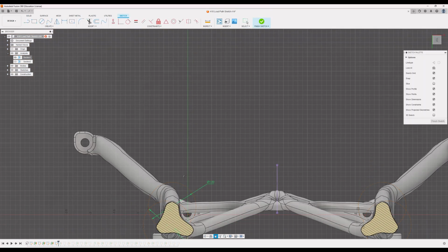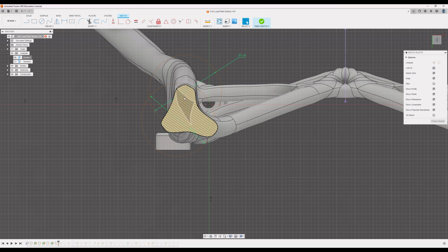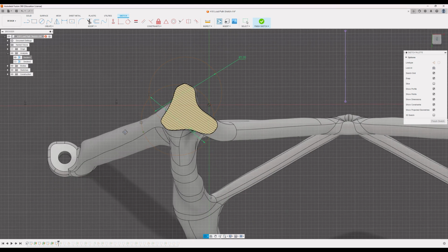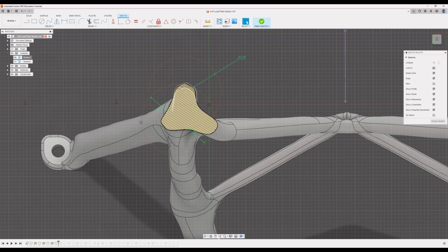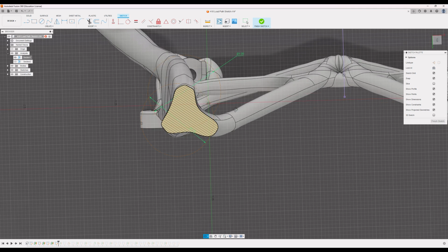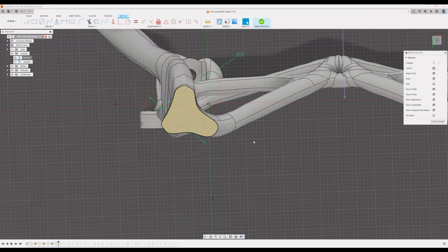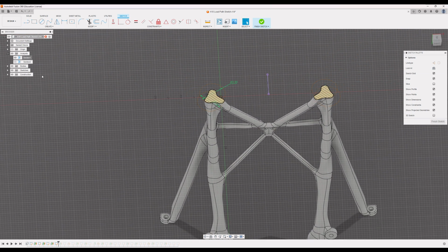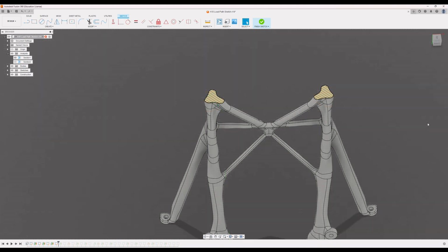So you can see here we have a point where we have 3 supporting structures that all meet at a triple node. Now these look intimidating at first, but you can see here in the profile it's very clear where these lie. Now on the inner one we do have what looks like 2 inflection points, so I'm only marking the outer 2 here because I'm mostly concerned about the outer support structure here as opposed to that inner structure. That inner structure we can begin to build out by using a section view from a different perspective, and that'll allow us to see it a lot easier.